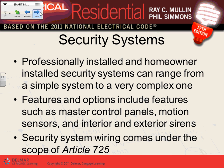And we'll talk about these when we go to the full spiel. Any question, guys, about the fire alarm before I move into the security system? So 72 tells you where to put them, sleeping area and hallways in the front of it. We need smoke detectors. Heat detectors, there's a lot of recommendation where to do them in dwellings, guys. It's up to us to decide where. If you want to go ahead and put one in the kitchen, that's fine with me.